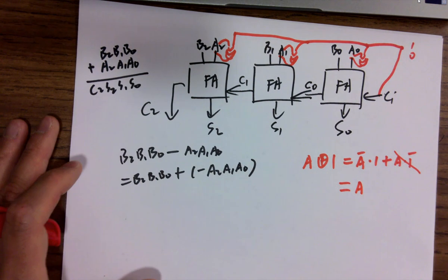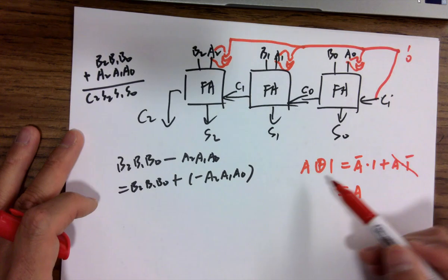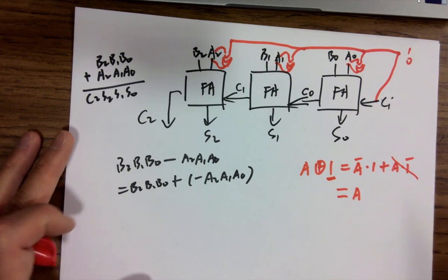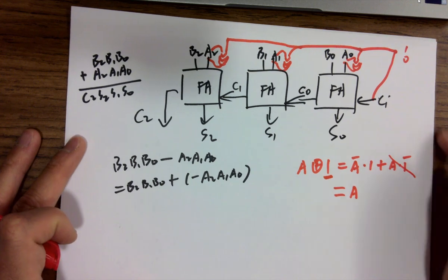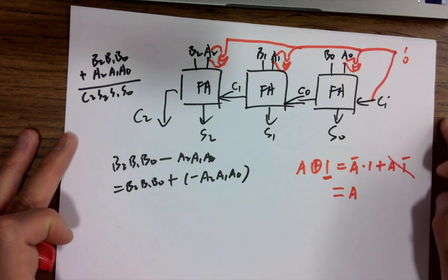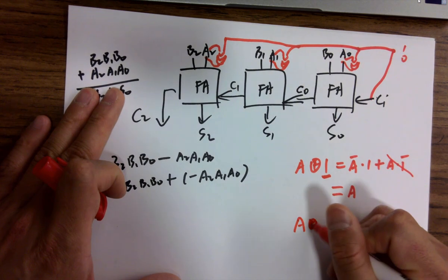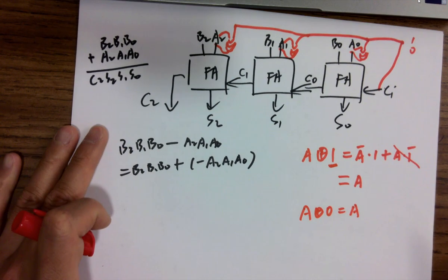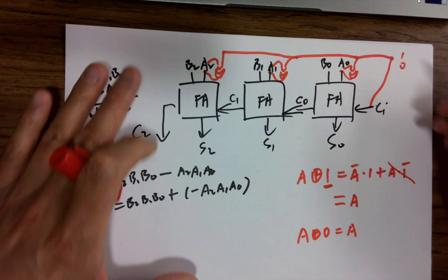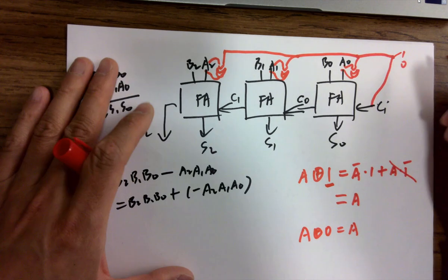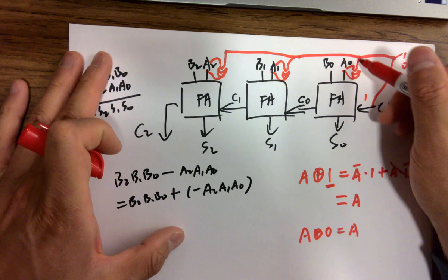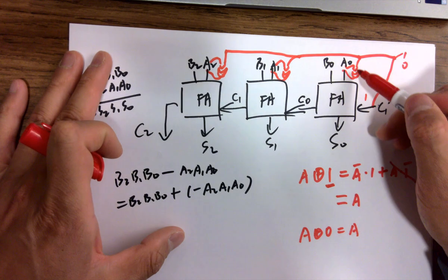So keep in mind, if you XOR a logic with 1, you are actually inverting it. That's a pretty important technique, a conclusion we use in digital circuit design a lot. If you do A XOR 0, it retains the value of A. It's not changing it. So if you put it to 1, you're adding a 1 to the overall input, but also you are flipping all the A's to their negative counterpart.